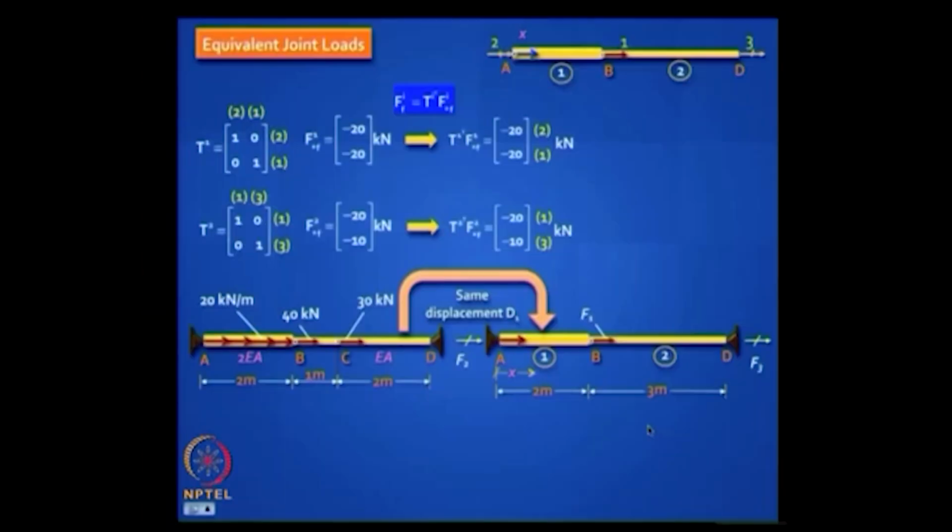So if you look there, you have to do this. Just pre-multiply by T1 transpose, which is no big deal because the transpose of an identity matrix remains an identity matrix. So the only purpose of doing this, you will end up copying the same thing, is now you are bringing in the linking coordinates. Is it clear? With the help of these two, can you identify what your fixed end force vector is? At the coordinate 1, these two will add up. That's what you are doing in the slot wise pushing. And at 2 and 3 it's known, so you can use these two and get your fixed end force vector. Does this make sense to you?